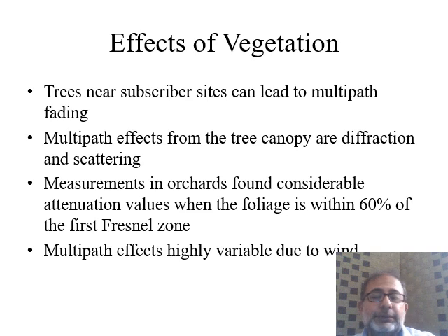First of all, we need to take care of the height of the earth bulge that comes in between. That determines, if there is no vegetation on it and the whole earth between the transmitter and receiver antenna has a normal curvature, that we only need to take care of the earth bulge.